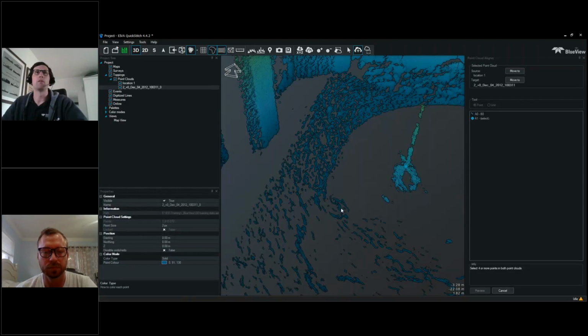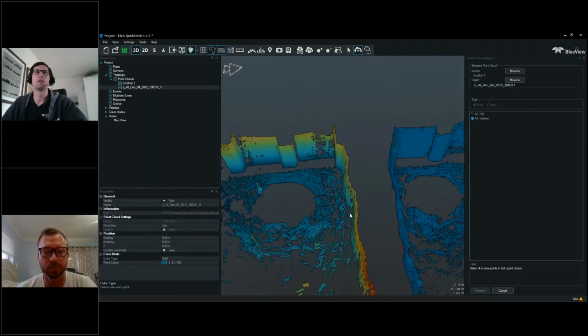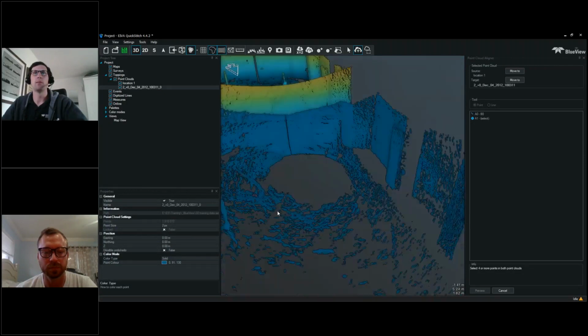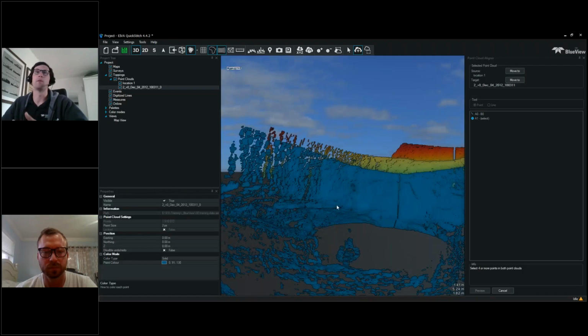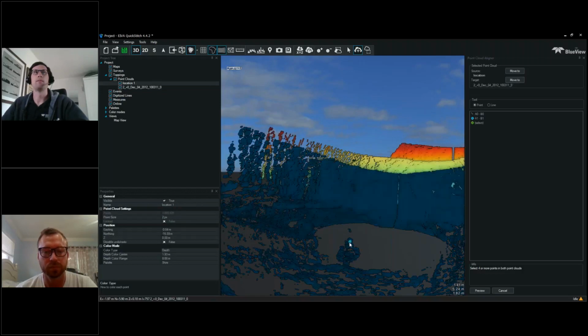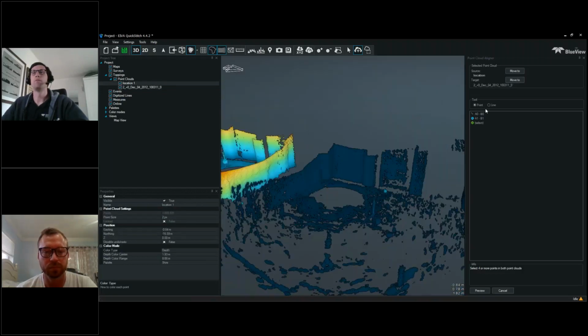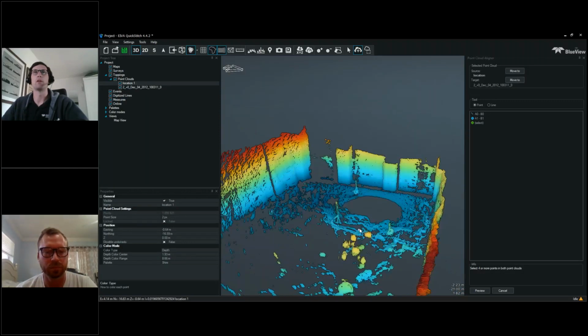And then I want to look for that same object, which is actually right here. Not as pretty, but it'll work. You know, it's not an exact science a lot of the time. The software is going to do a lot of the hard work, but you want to be as close as you can with your point and line designations. Okay, so we have 2. Again, I need 4 or more to really allow the software to do anything at all.